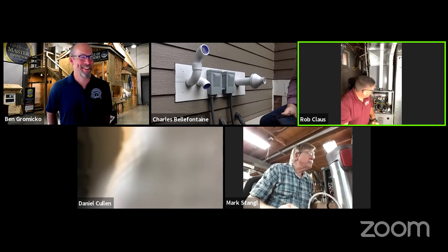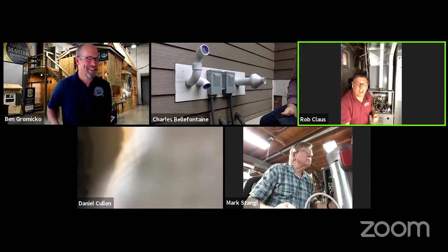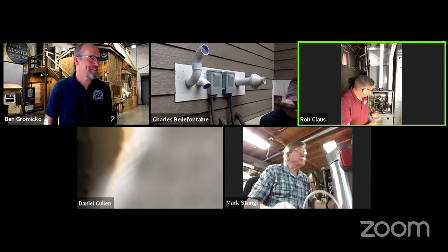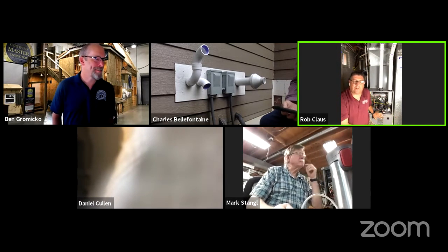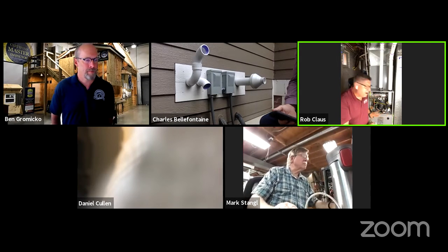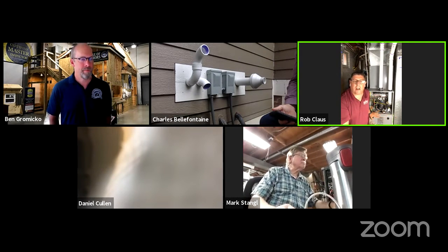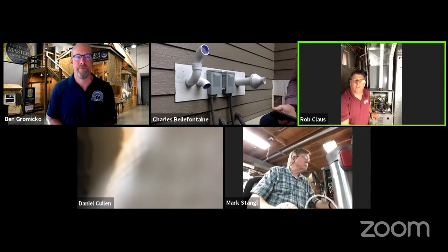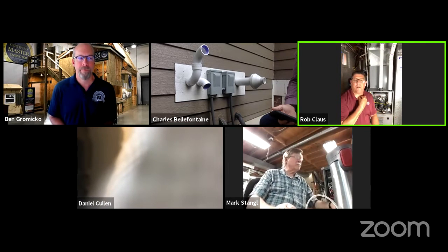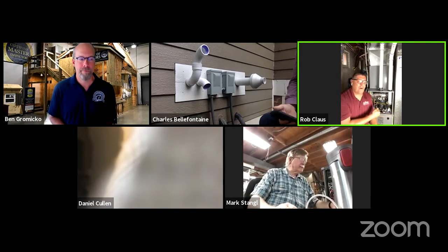But what's also interesting, like Dan does and like Charlie does, is they walk their clients through these systems. I'll tell my clients to take the cover off these things. Stare it down here at a high efficiency furnace in the condensate. You see moisture? Call a tech. Just as simple as that. I see rust, I see scale, I'm going to put it on my report. But you let your clients know where their pitfalls are, you're good to go. You can move on from there.